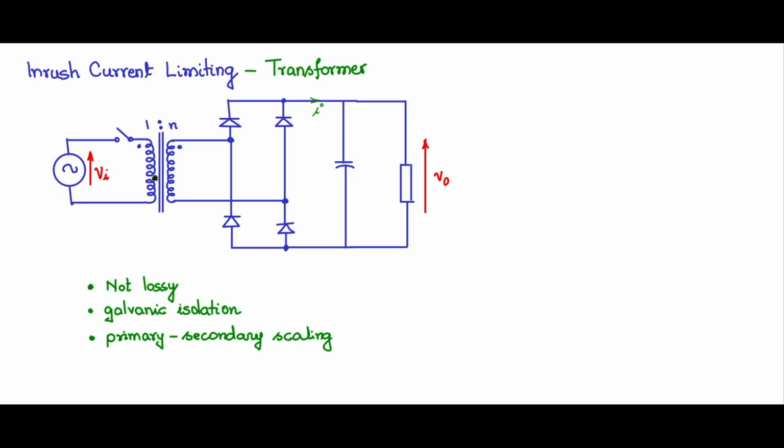Whereas in the case of the one without the transformer, the output voltage is linked tightly to the input voltage amplitudes and fluctuations. Another advantage is the inrush current limiting, and that is why we propose the solution. So inrush current limiting is a natural spin-off by putting the transformer. I'll tell you how this comes about. If we draw the equivalent circuit, you will see that there are leakage inductances which will prevent the first cycle current inrush happening.